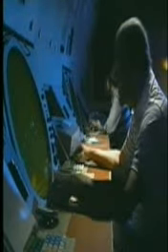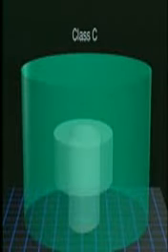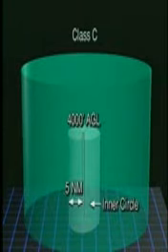There is also an outer area that extends out to 20 nautical miles from the primary airport. The ceiling of this area extends up to the limit of each approach control's delegated airspace, and the floor extends upward from the lower limit of either radar or radio coverage. Therefore, the vertical limits of this airspace vary for each Class C area. The altitudes of the inner and outer circles of Class C airspace are depicted on sectional charts, and the lateral limits are outlined with a solid magenta line.